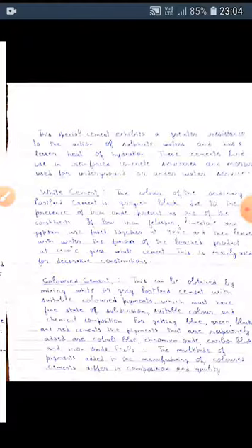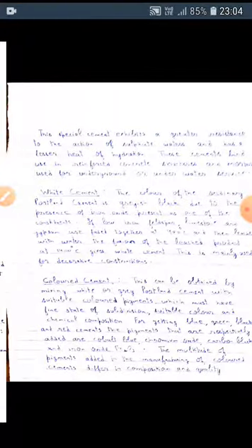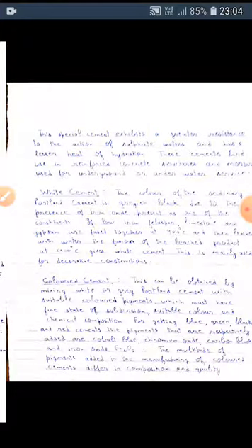That is why pigments and the raw materials are checked for light stability and alkali resistance. These coloring agents should not reduce the strength, frost resistance, water permeability, resistance to weathering, and other properties of mortars and concretes. It should not impair the paint applied on the surface of the colored cements.